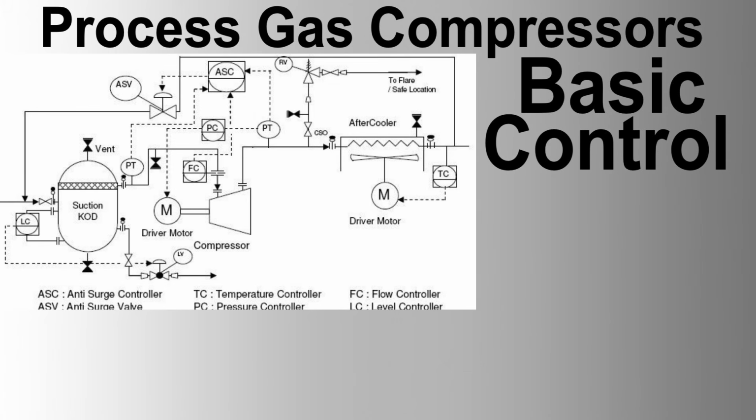Now, 3. Interfaces with the DCS, distributed control system. A. Signals to the DCS. Speed set point, desired speed for the VFD provided by the DCS. Torque set point, desired torque if torque control is utilized. Start-stop commands, commands to start or stop the compressor.